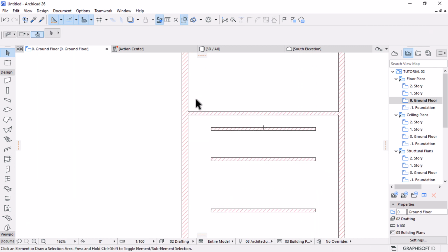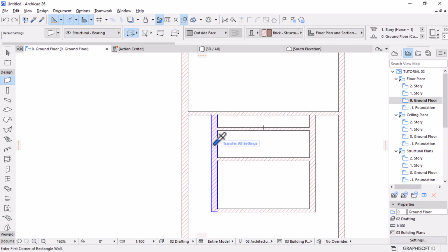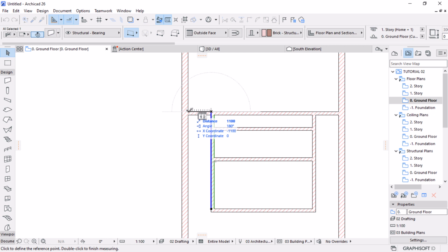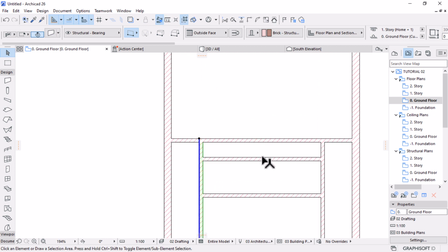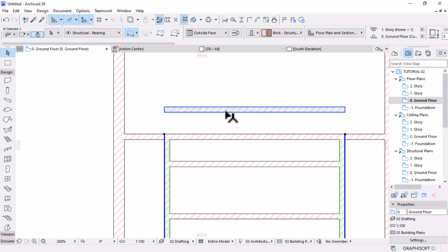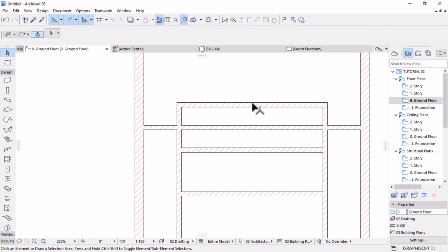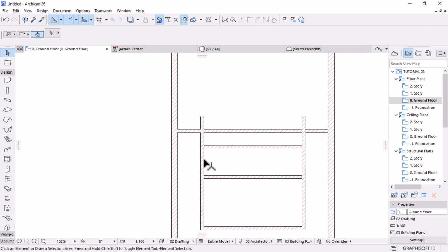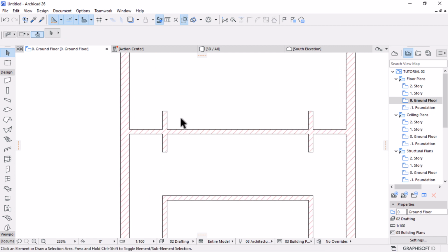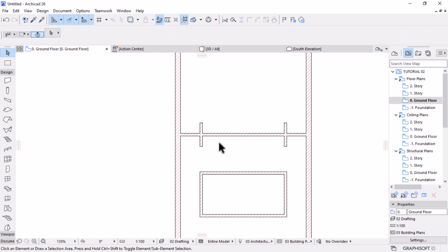And then I need to, okay, no, let's say undo. I need to pick parameters of this and then make this also an internal wall, right? Make sure you confirm the width is 1.1, which is what I want. And then I can mirror this wall to the other side. I'll use the center of this wall to move it that side, and then these two, I'll select them and then intersect them like that. So this can go, and then I can trim off this there, and then I can get rid of this, because here is to be a closet for the inside of the bedroom and then the outside.